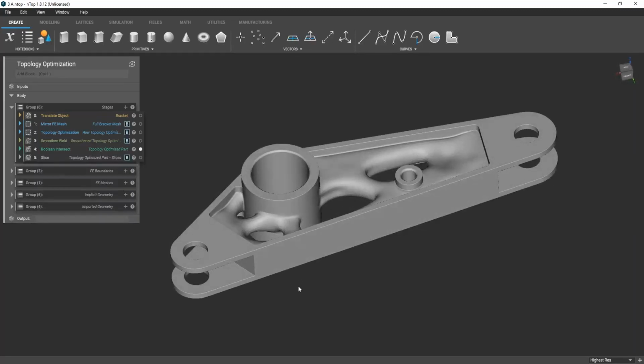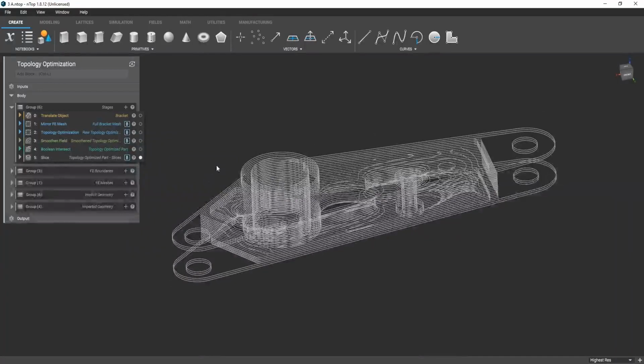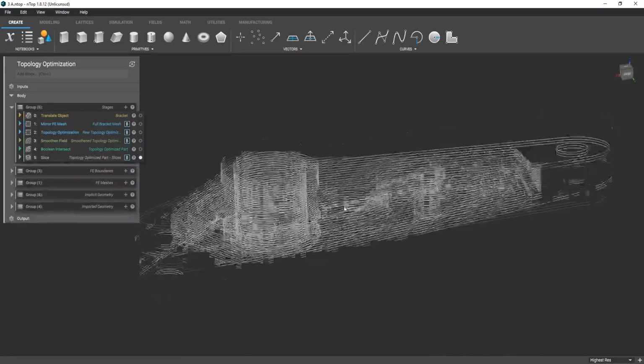With this, we now need to get the part off the screen and physically into your hands. Our manufacturing output can be your traditional surface mesh, such as an STL or an OBJ, both of which are recognized universal formats in the additive manufacturing ecosystem. But what we can also output is contour slices. These can be ported directly to your machine's processing software, so you can bypass those heavy STLs.